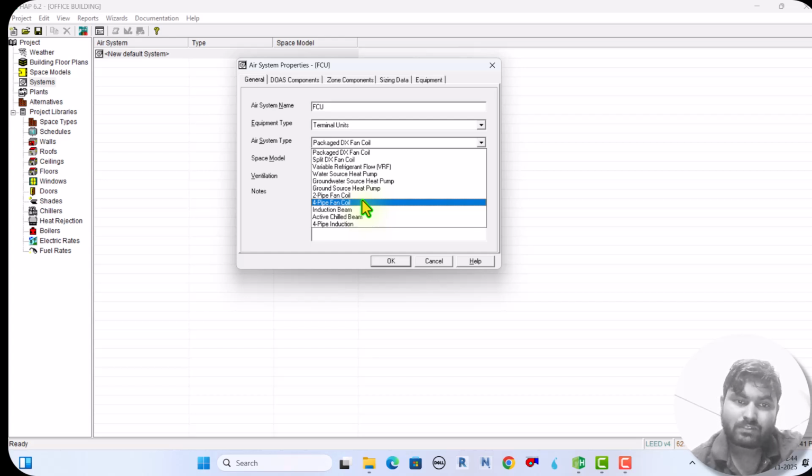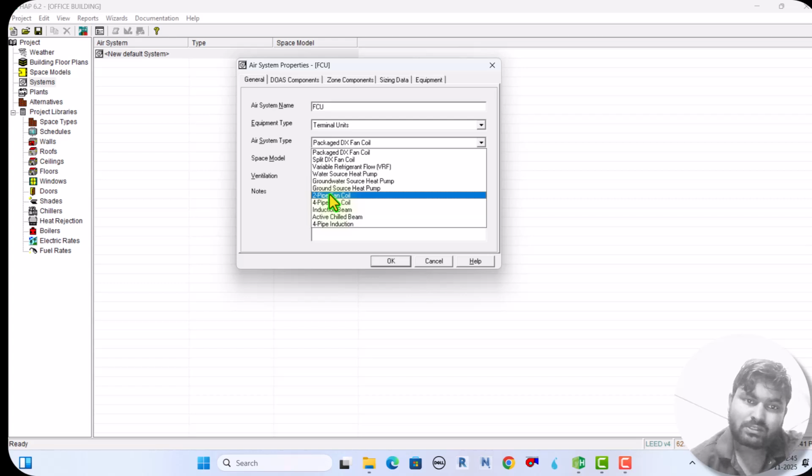In the cooling system we can use the chilled water system, and for heating pipe we can use boiler water, like hot water, the water which we can generally take from the boiler. So the 4 pipe we can use, but it is costly compared to the 2 pipe fan coil unit. But I am here doing the cooling load calculation, so it's better to choose 2 pipe. One pipe for supplying the chilled water and one for return, total 2 pipe.